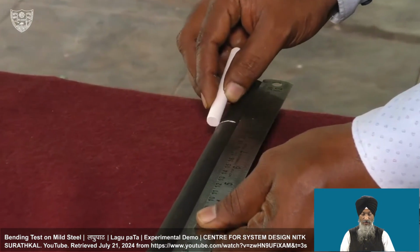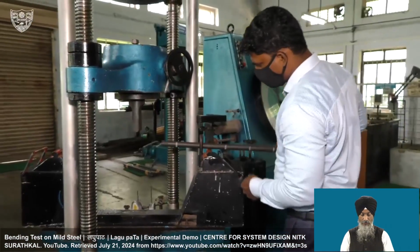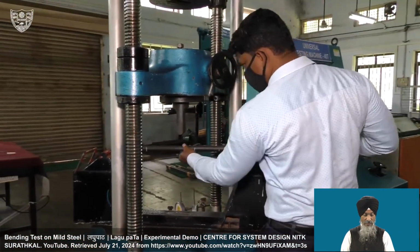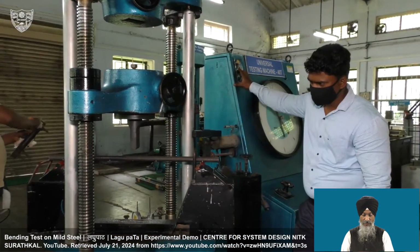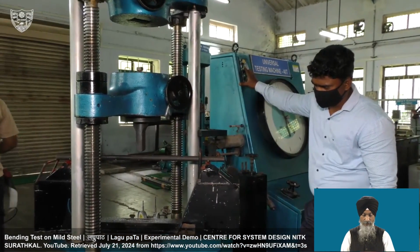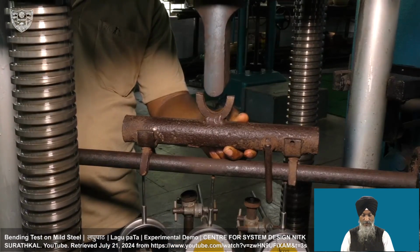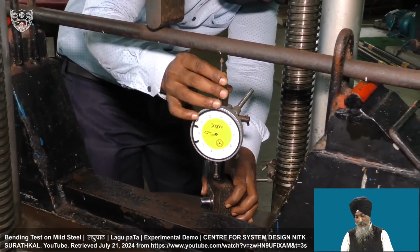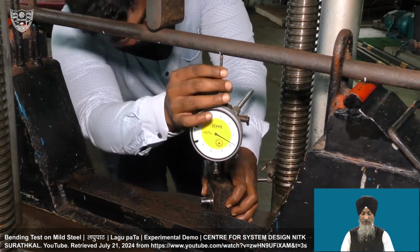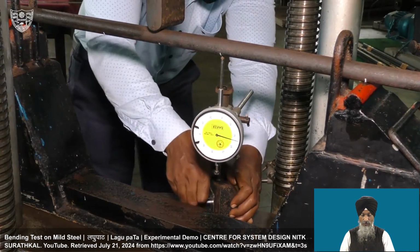The marking is in place for the 1/3 loading points and the mid span where the dial gauge has to be placed. This is our bending fixture, which is set up so that the load is applied at the 1/3 span. Now, dial gauges are put down exactly at the points that were marked. There is 1 dial gauge at the mid span and 2 dial gauges at the 1/3 spans. So, 3 dial gauges are now being set here.